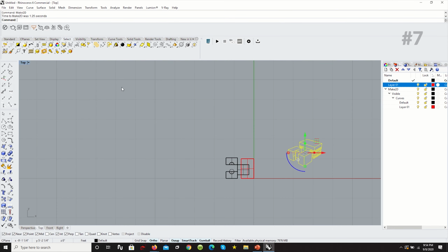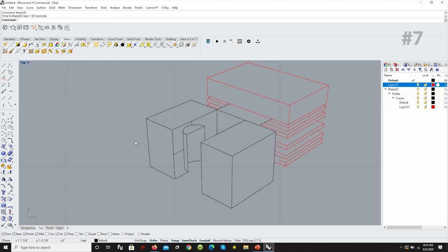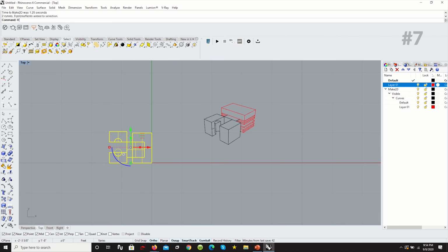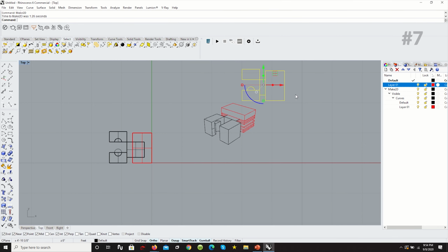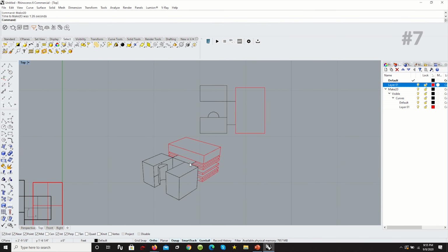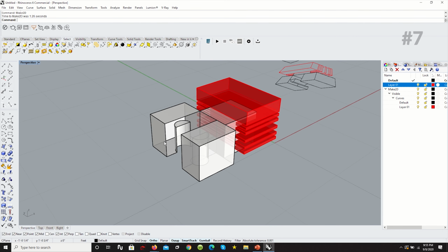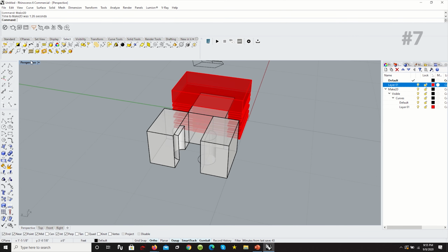And if we go to the top view, we can see a two-dimensional outline output of what we just made. If I was to do this from the top view and hit make 2D, we don't want hidden lines, we just want a basic make 2D. You see, it's completely different from doing it from my perspective view. Even if I was to orbit a bit and do make 2D, it will always come out different based on what my current view position is.